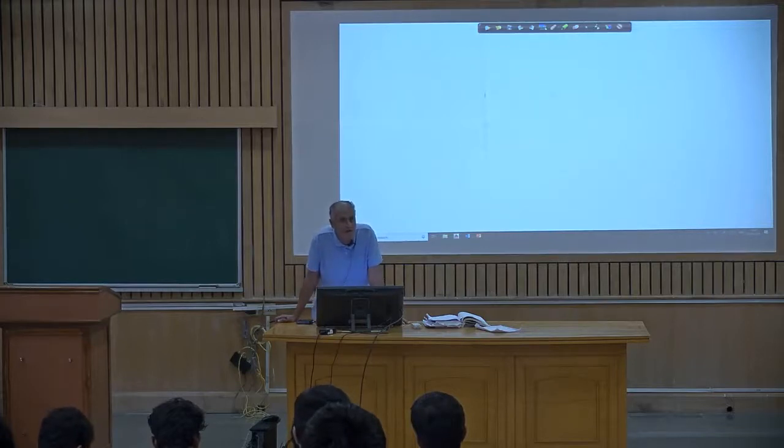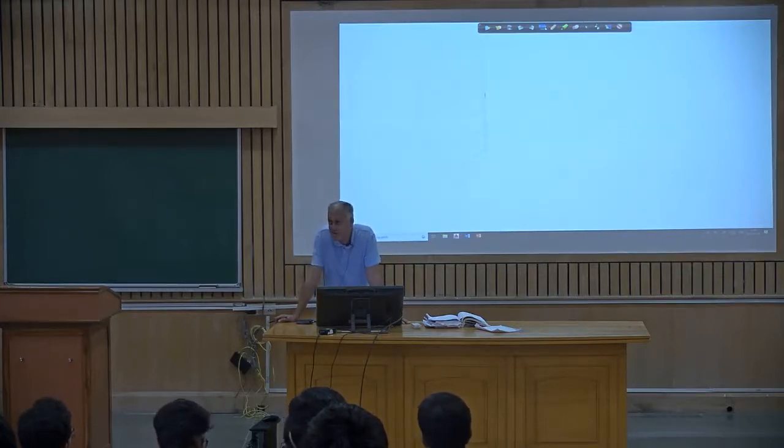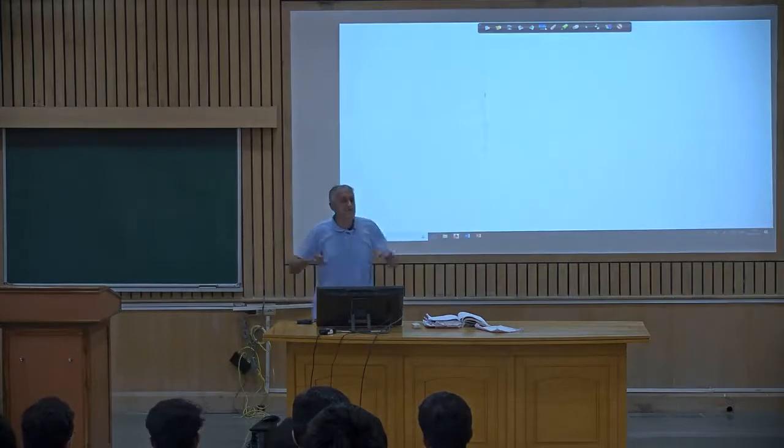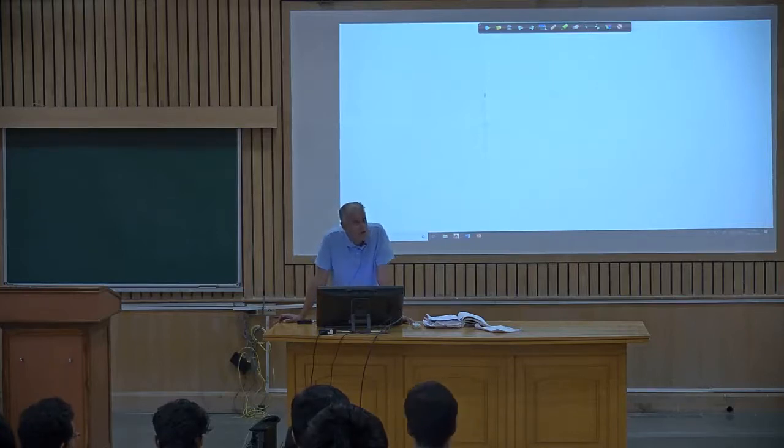So only if I say steady state process, you eliminate time. If I say steady flow process, you don't eliminate time, you say it is constant. That's the difference between steady state and steady flow. Steady state, you don't worry about time, you eliminate time. Everything's equilibrated as though you have waited for infinite time. Steady flow, it's constant with respect to time. There is a number.